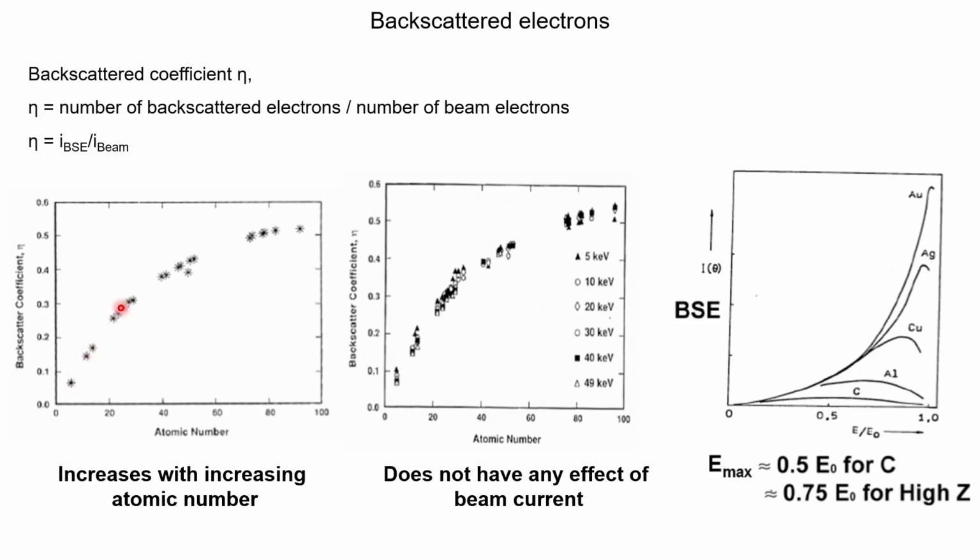So the distance between these two will be higher as compared to two atoms which are already at higher atomic number. At higher atomic number, the slope is very small, so as a result the backscattered electron coefficient difference is also very small.